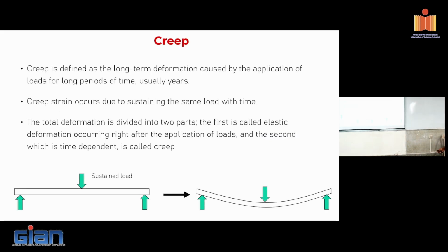Now, more than 0.5% of fibers would reduce the strength of the concrete? Actually, with steel fibers, when you mix properly and don't have a walling effect, the strength should not come down. We have tested several of them. Strength goes up by 5-10% depending upon your mix, but it doesn't come down. But when you are using polypropylene or synthetic fibers, you have a weaker interface, so the strength reduces slightly. With steel fiber, strength typically doesn't come down. It can go up depending upon your mix.